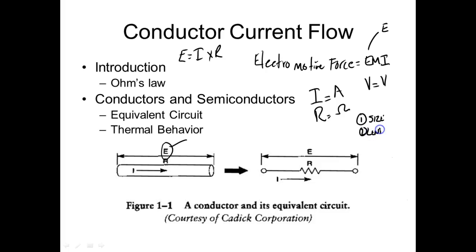Length. Material. Somebody said that already. And there was some before. Well, sort of. It's actually the temperature. But the insulator affects the ability of the conductor to get rid of the heat that's being generated by the conductor. So this is why NEC people don't understand this. So they rate the ampacity according to what insulator you use, because that insulator determines how easily that conductor can do what? Get rid of the heat.